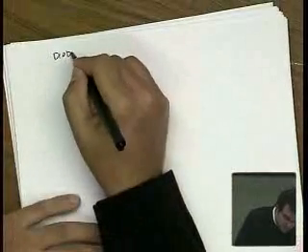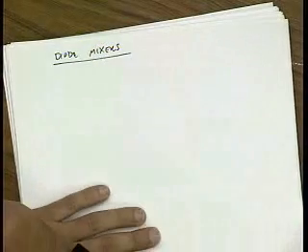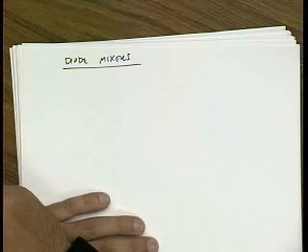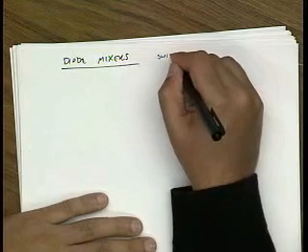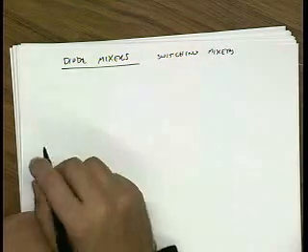Okay, let's now look at diode mixers. Now, diode mixers are actually practically very important. They're used a lot for high-frequency circuits. Effectively, they're also like switching circuits, so they're like switching mixers. So what we're going to do is use the diode as a switch.